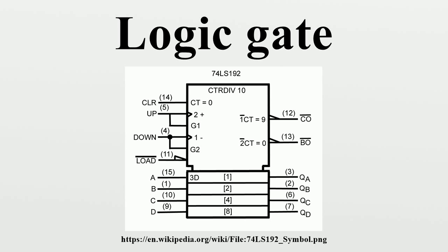IEC 617-12 and its successor IEC 60617-12 do not explicitly show the distinctive shape symbols, but do not prohibit them. These are, however, shown in ANSI/IEEE 91 with this note: The distinctive shape symbol is, according to IEC Publication 617, Part 12, not preferred, but is not considered to be in contradiction to that standard.